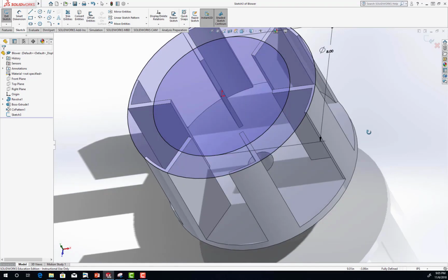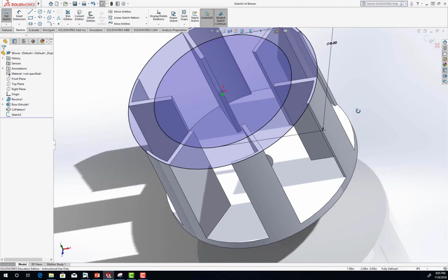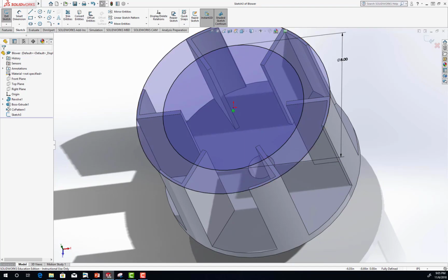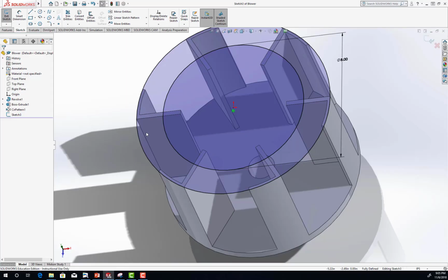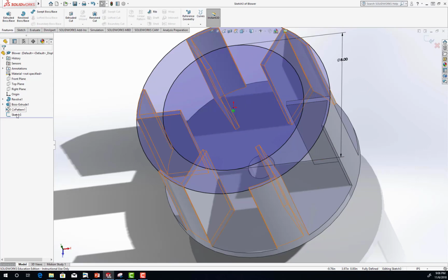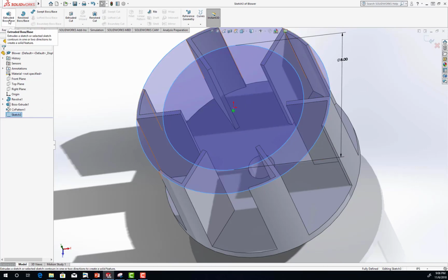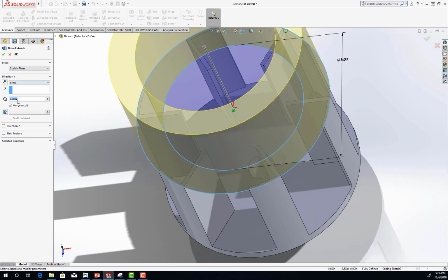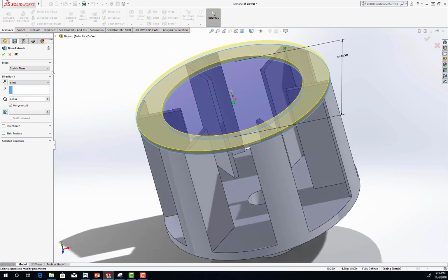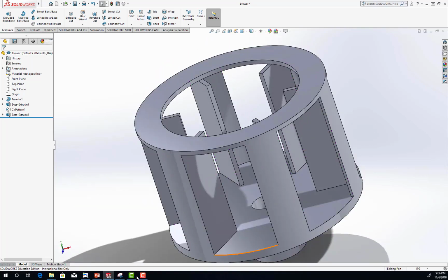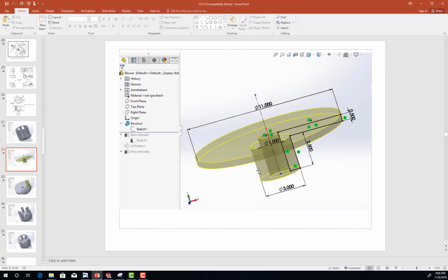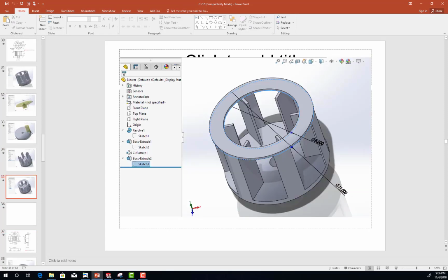And now we are going to extrude that part up. See if they will recognize, not sure, we'll try. And the thickness is going to be 1/4, okay? And go back to SolidWorks, features, sketch 3 we just made, and extruded boss or base. And make the distance 0.25. And going up looks right, and say OK. Okay, so this is the part, and that's the last step as well, I think. Yeah, that's the last step.